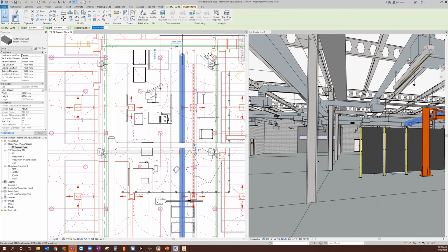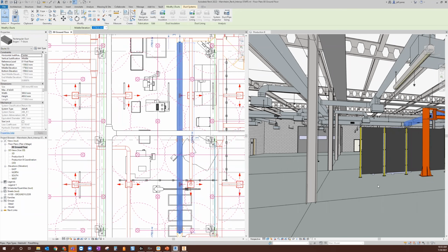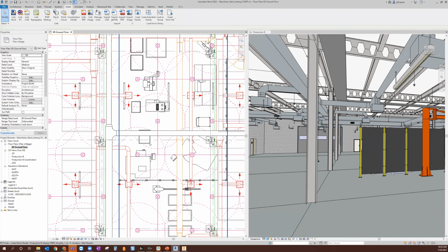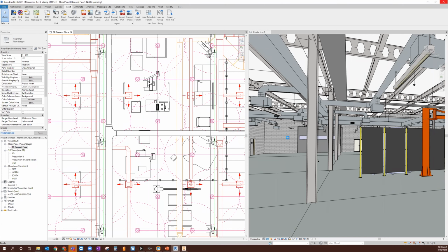Okay, so now it's not clashing there anymore. And I'm seeing that here now. So now that ductwork is moved, it's cleared. What I'll do now inside of Revit is I'll click Save. So we've cleared it. The mechanical firm has determined that, okay, the clash is no longer there. They're going to save that file.